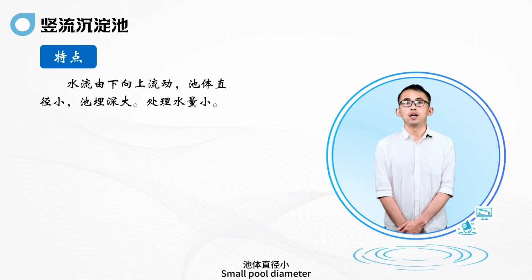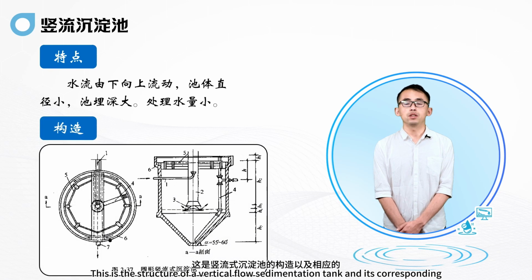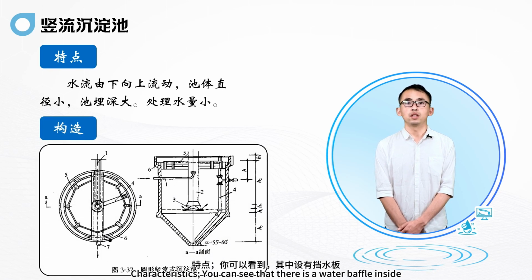Small pool diameter. The burial depth of the pool body is large. Low processing water volume. However, it occupies a relatively small area. This is the structure of a vertical flow sedimentation tank and its corresponding characteristics. You can see that there is a water baffle inside, and the separation of mud and water happens from the middle to the surrounding area.